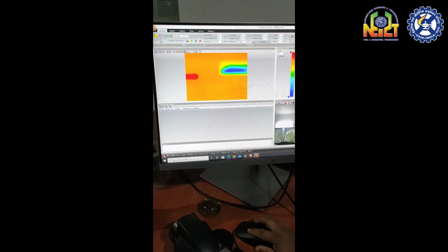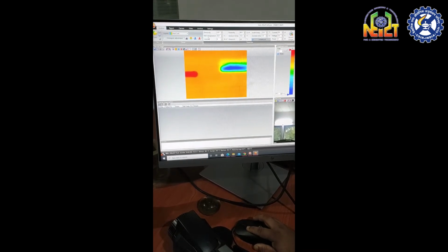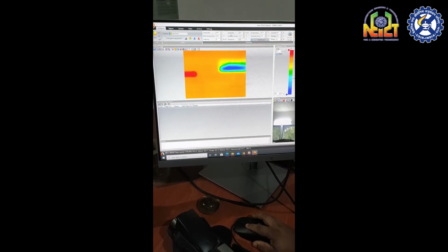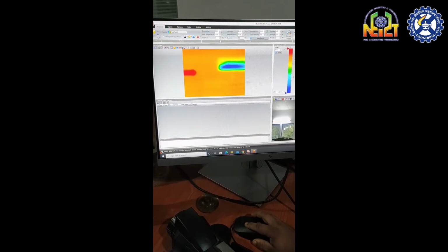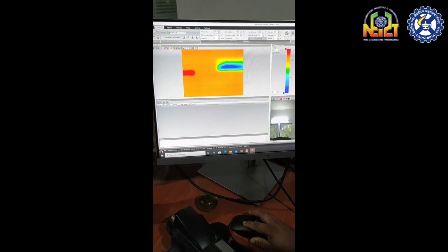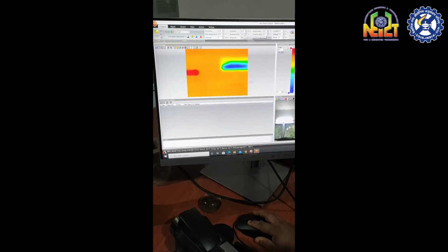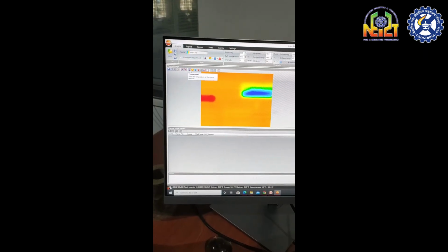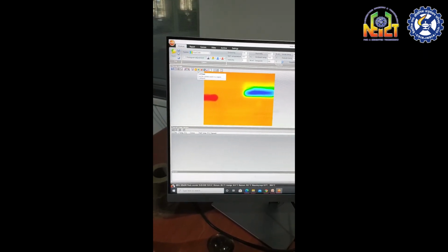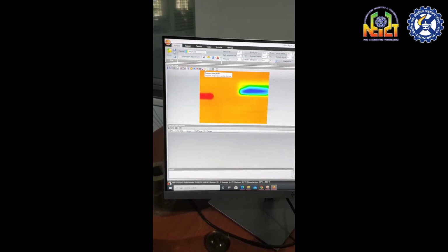For image processing, first you have to insert different data like emissivity, reflected temperature, humidity, and ambient temperature. We have inserted emissivity 0.95, reflected temperature 20 degrees, and we consider ambient temperature 14 degrees, and humidity is 40. In this tool bar you get different options like temperature correction, cold spot, hot spot, then histogram, temperature profile.